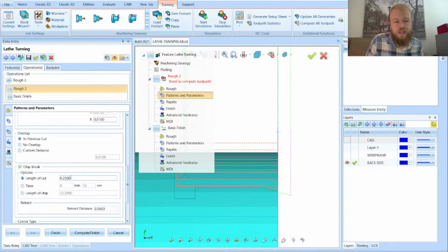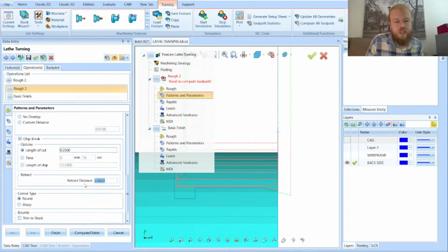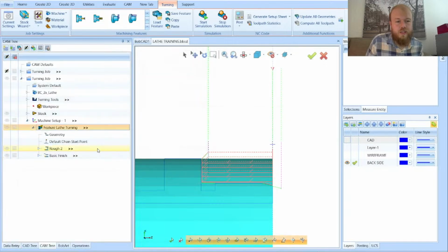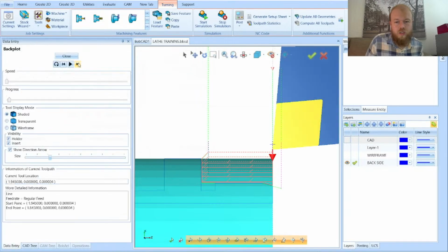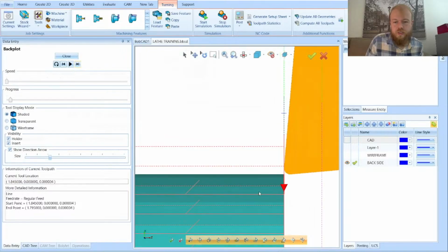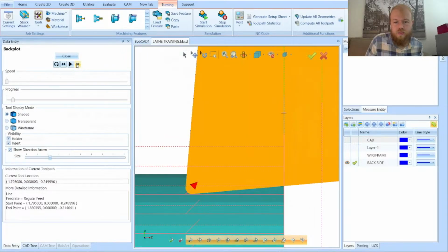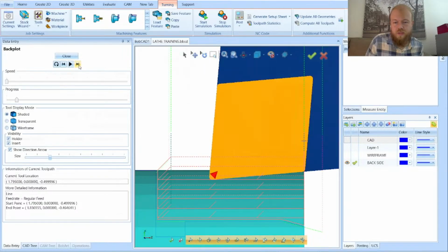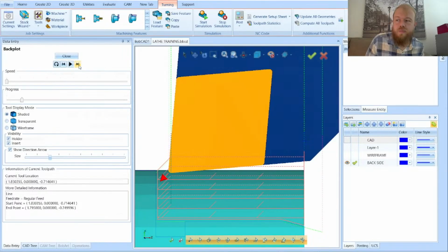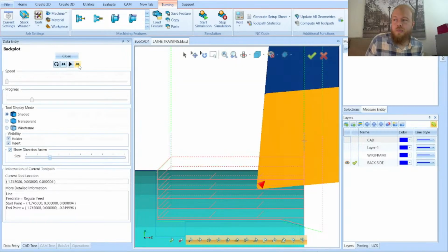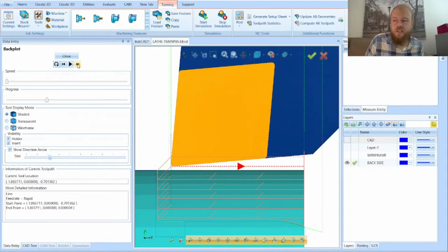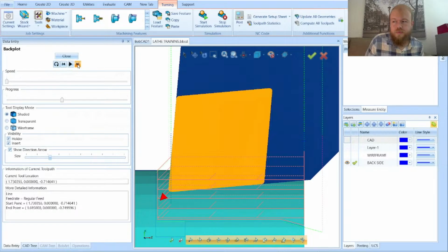You can set the length of the cut and the retract distance here. So the length of the cut as a 1/4 inch here will go across a 1/4 inch right here, and then it'll retract 50 thou that I set, and then come back down, and then go across a 1/4 of an inch each time. So that chip break option allows the tool to retract just a small amount as it's roughing, so that it doesn't have any built up material as it goes across there.